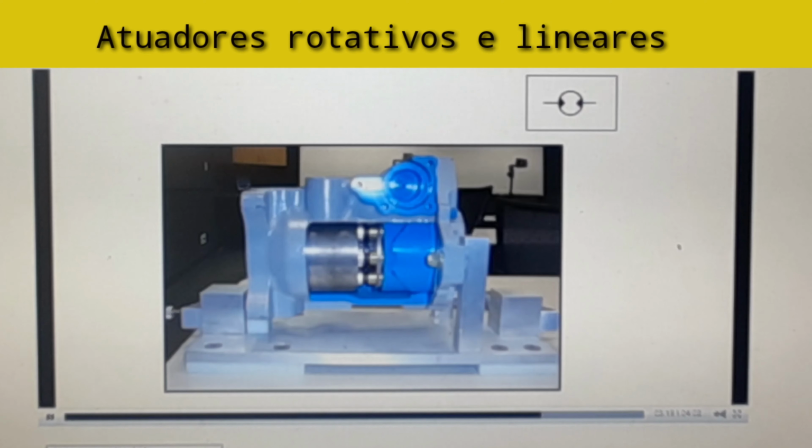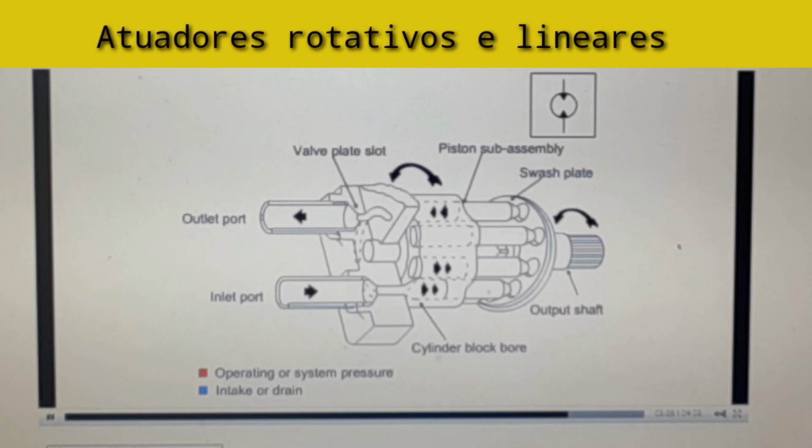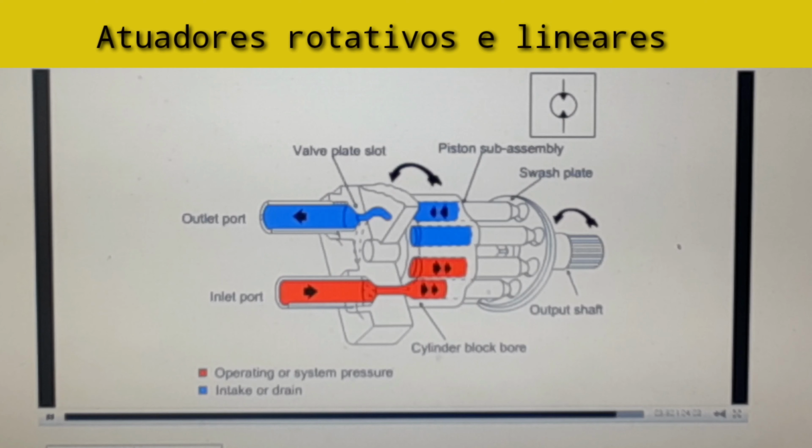While the gear motor is a simple design, the piston motor is commonly used in high pressure, high flow, and variable displacement mobile hydraulics applications. Just like the piston pump, the pistons in a piston motor are mounted in a revolving barrel and slide in and out of the bores along a swash plate. Fluid is supplied to the pistons on the high pressure side, forcing them down the angled swash plate. The pistons are fixed in the barrel, causing rotary motion. The barrel is mechanically connected to the output shaft. As the motor turns, the fluid is exhausted to the low pressure side.